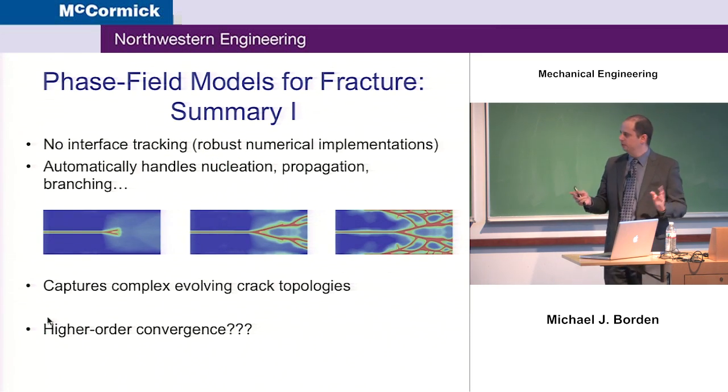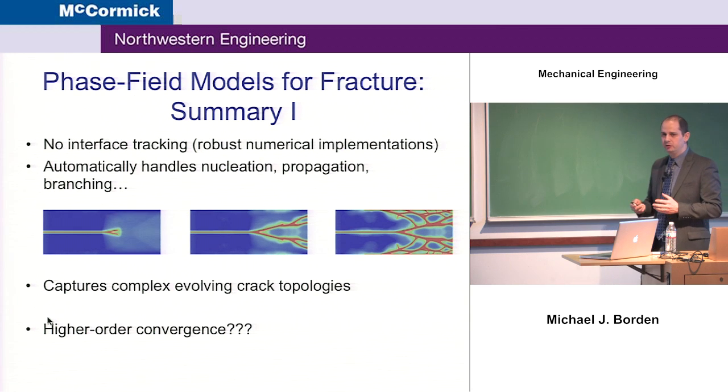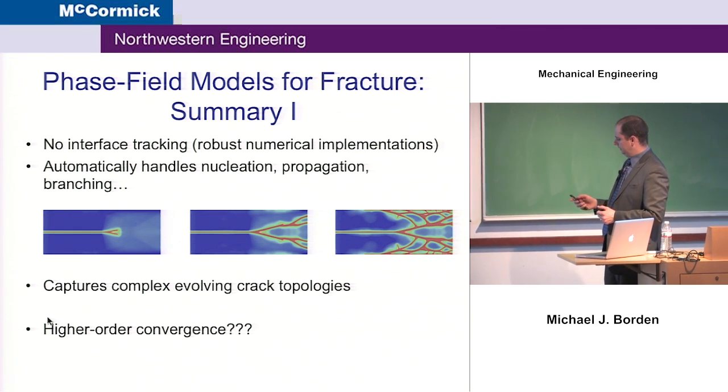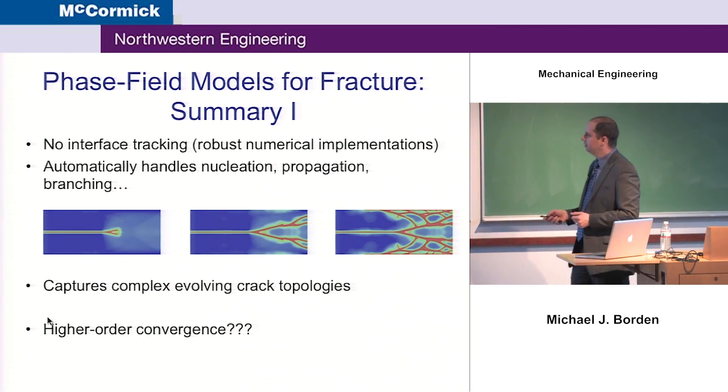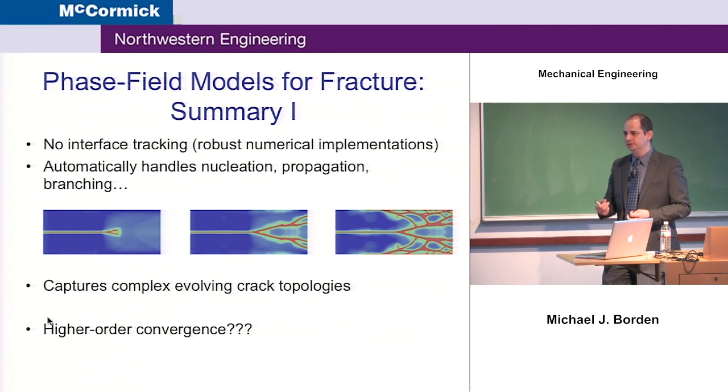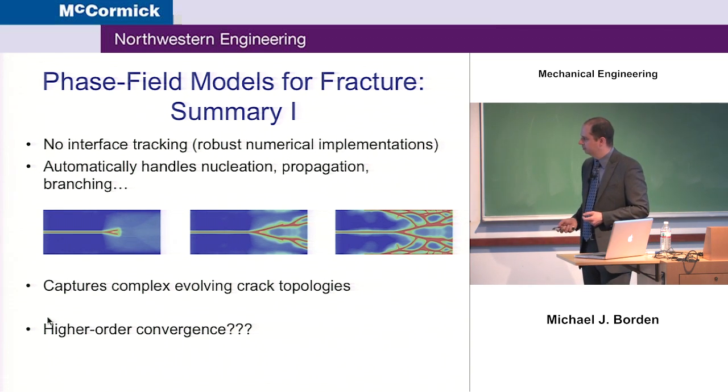So just a brief summary of what I've talked about so far. We've introduced the phase field model. It has no interface tracking, so it's a robust numerical implementation. It's robust in both 2-dimension and 3-dimension. It automatically handles nucleation, propagation, and branching, these complex crack topologies.